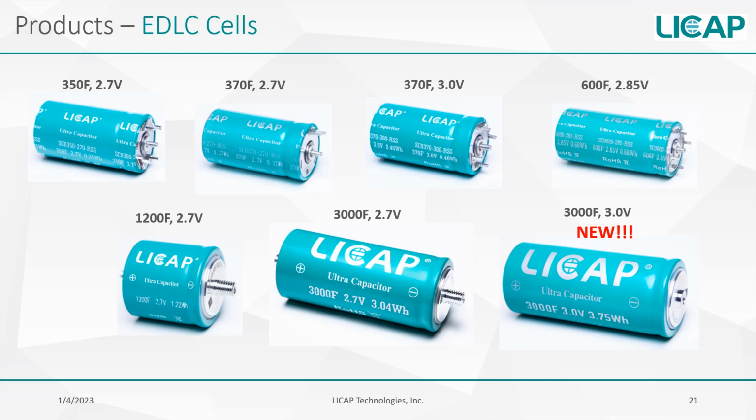Now let's talk about our EDLC or ultracapacitor cell product line. In the top row, we have our D family size series of cells ranging from 350 farad 2.7 volt, 370 farad 2.7 volt, 370 farad 3 volt, and 600 farad 2.85 volt cells. In our larger family of cells, we have 1200 farad 2.7 volt, 3000 farad 2.7 volt, and 3000 farad 3 volt, our newest cell. These cells all are available in the modules that we'll talk about next.